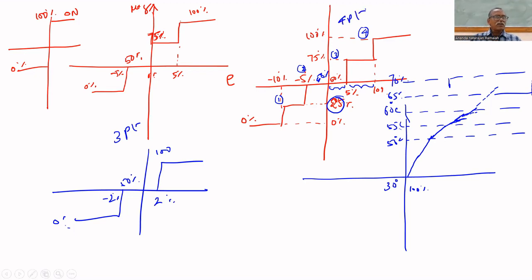But the ideal on-off controller is a 2-point controller. We made 3-point and 4-point. If we increase the number of points, we can expect less overshoot. But again, it is wandering around the set point. It never settles at the set point, because the controller does not know the value for which it will settle at the set point. That's why it is not possible to make the set point equal to PV.